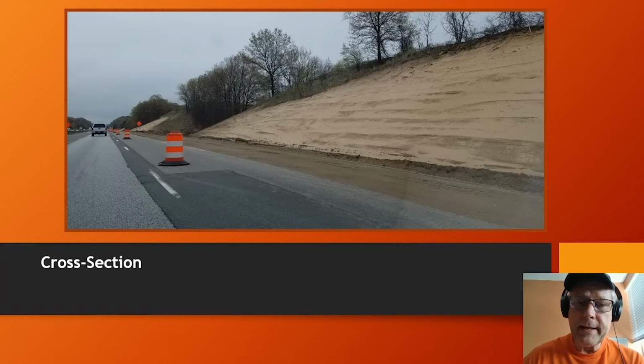This project here had a contractor building a new shoulder, and you could see all the moisture that was coming downhill for quite some time. So they never actually had the opportunity to build on a dry foundation. Some type of an interceptor pipe would have been better at the toe of that hill to collect the moisture, something like an 8 or maybe even a 10-inch diameter perforated pipe, and then to outlet the water into a ditch somewhere else. This right side of this roadway has been challenged for years because of the moisture that continues to get under the pavement. The right lane in this particular case has been milled and overlaid several times because of moisture from below. So really want to take care of that foundation in every case so that our pavement performs better.